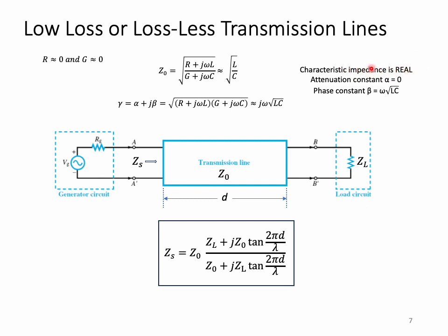In general, that's not the case. You buy coax at 50 ohms, you are approximating a characteristic impedance of 50 ohms, but it's not quite there. We'll see that in some view graphs further on. The attenuation constant now you can show is equal to 0. In other words, there's no attenuation along the line, but the phase changes, obviously, as a function of the position.